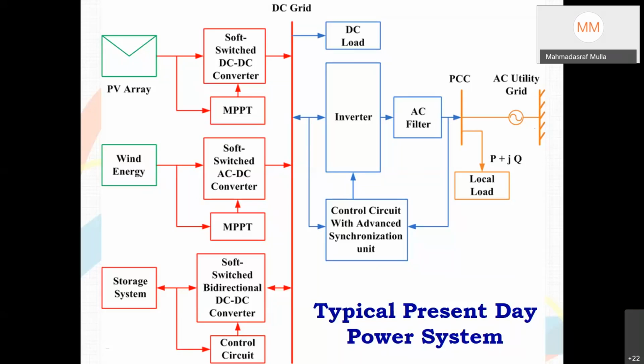So wrongly, many of the times when we speak about power quality, like I am having a variable frequency drive, we will say that my motor terminal power quality is not good. We should talk about power quality only when the utility grid is interfaced. So power quality will be of concern only with the utility grid.